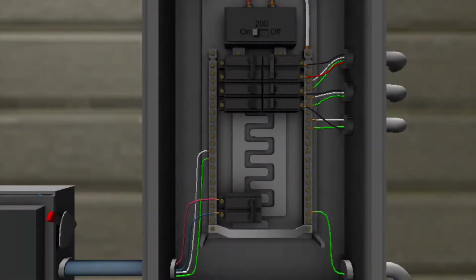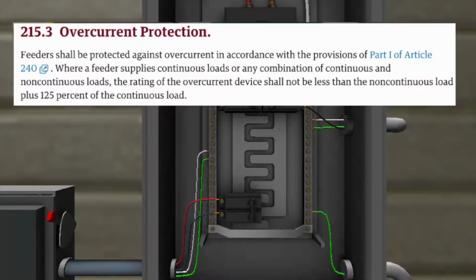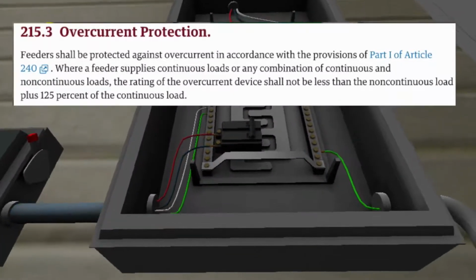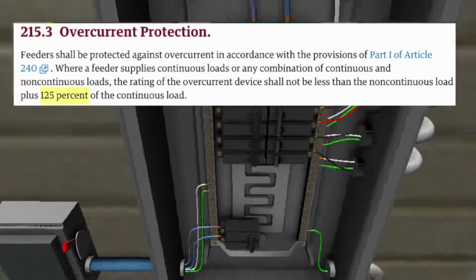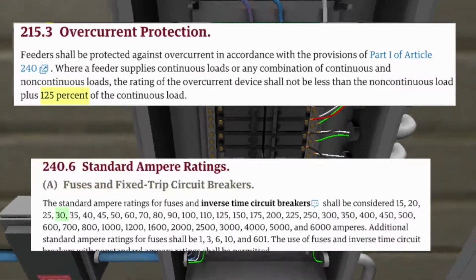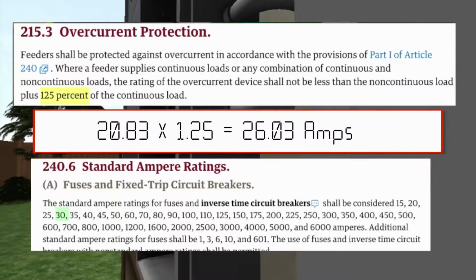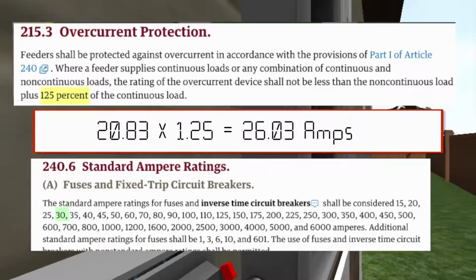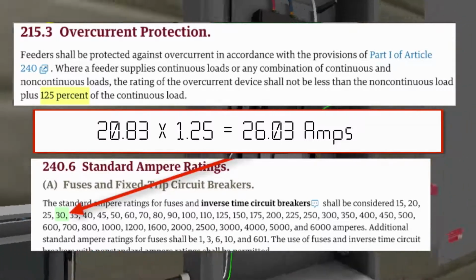Per NEC 215.3, the breaker size is determined by taking the current value, multiplying it by 1.25, and then selecting the next larger breaker per 240.6. 20.83 amps times 1.25 equals 26.03 amps. The next largest breaker size is a 30 amp breaker.